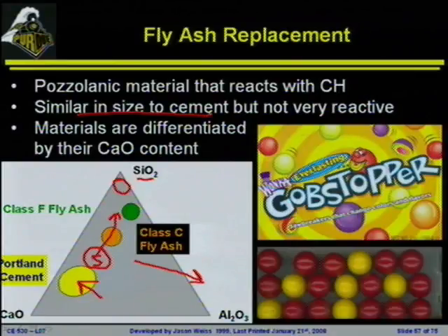Now, there is one material that's out there that's a little bit different than this. And you will hear there's a specific company that markets it as an ultra-fine fly ash. This is basically them using something like a cyclone or a centrifuge to get rid of the big particles and keep only the small particles. Why would they want to keep only the small particles?